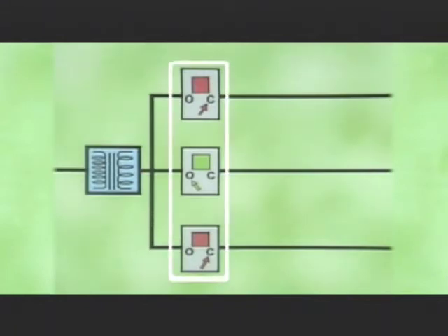The basic purpose of a circuit breaker is to protect its associated feeder from damage due to faults. Now, there are a number of different types of faults. For our explanation, we'll consider only a ground fault. A ground fault is a current flow path to ground that is not a normal part of a system's design. For example, under certain conditions, a tree branch coming in contact with a distribution line can cause current flow to ground. A malfunctioning component on a utility pole can also cause a ground fault.